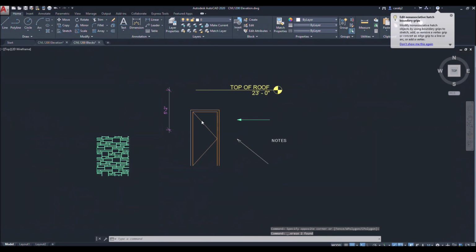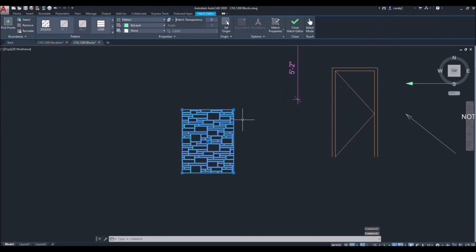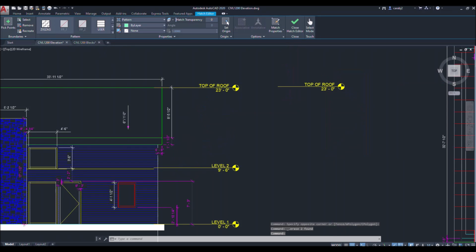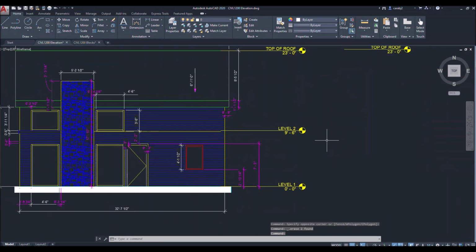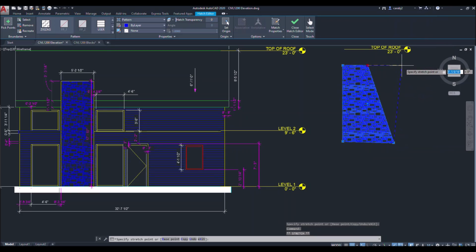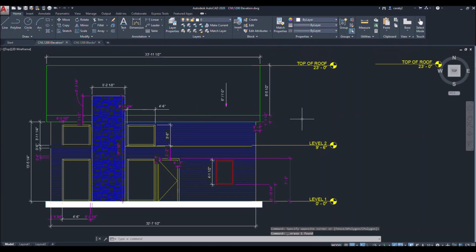So the same thing for this hatch. You will not have this hatch as the default in AutoCAD because it's like a stone. You can see here that it pops up as this one with like a slash through it. So what you can just do is select it and then copy it from that file by Control C. Going back to your other file, Control V, and then you can see how you can adjust it by stretching it out, making it wider, or adjusting the endpoints how you need to. So it's just a quicker way to do that hatch.